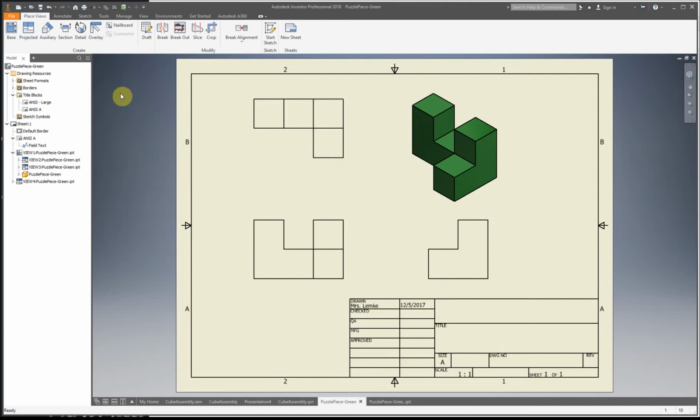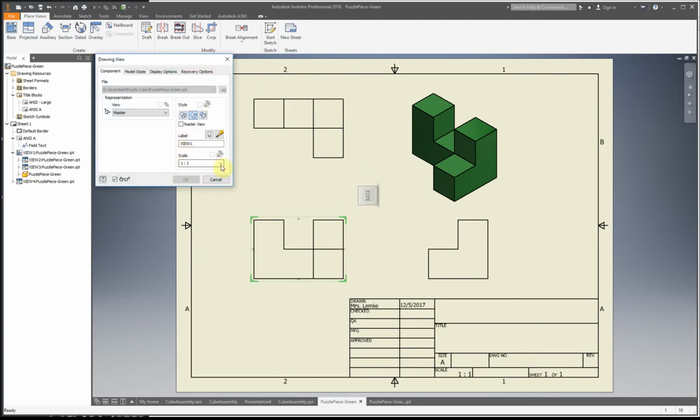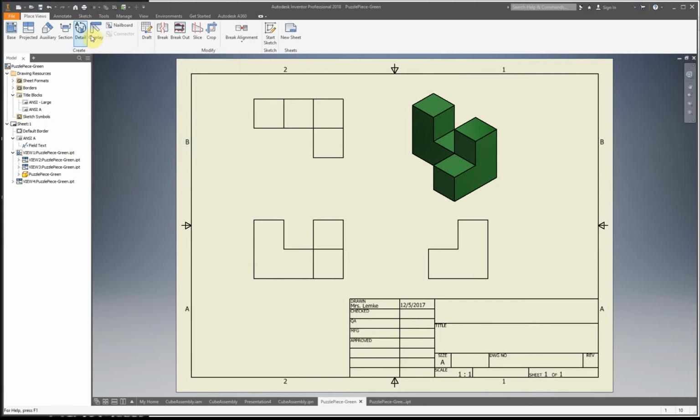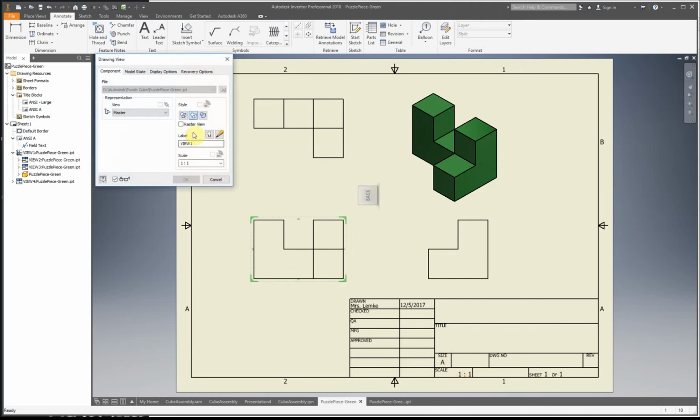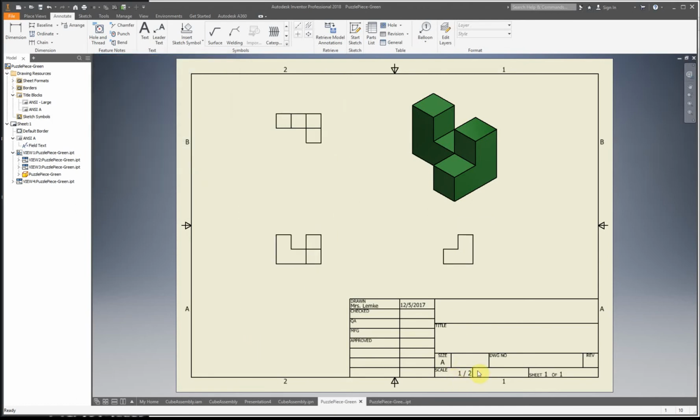So the next thing I'm going to do, I'm going to double click on this again. Our scale is right here, so 1 to 1, 1:1. The reason why I'm mentioning that is we're going to go to Annotate, Text, and ooh, that's neat. All right, so our scale, we don't actually have to type that in anymore, which is great. Actually, I'm going to change this to see if everything updates. Yep, it updates automatically. Since I changed this, you can see that this updates automatically, so it's one little change that we don't have to do ourselves anymore, which is kind of nice.